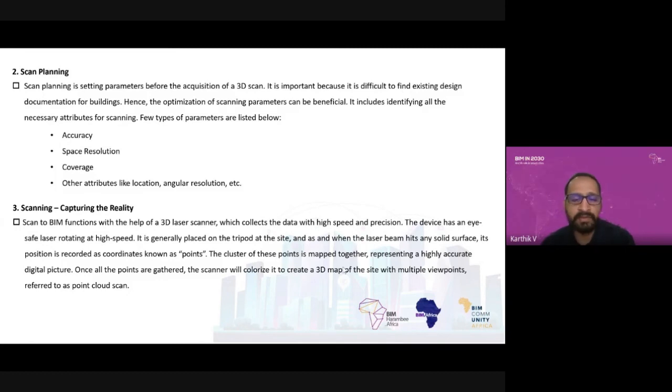It depends how fast your people can work, then accuracy, even the number of scans, like how many times you are going to scan, whether at a distance of 10 feet once or 5 feet once. It depends, but still you can do at least 100,000 square feet in one day. So this is for your easy calculation of how fast you can do the scanning.